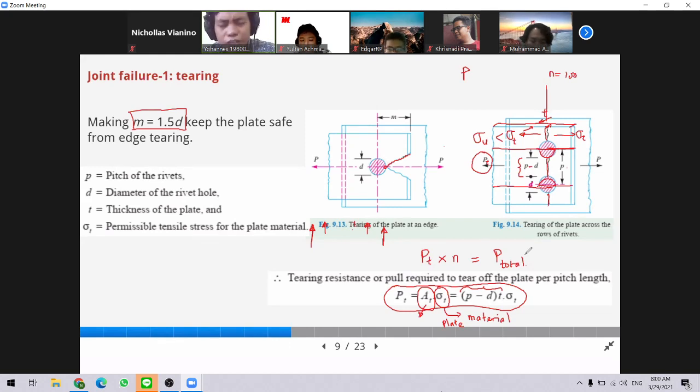Even if we use very thin plate, it still has a bending moment working there, even if it is small. And even if it's small, it can still bend the plate because the plate is very thin and becomes very elastic. So if we want to avoid the bending moment in the joint, we cannot use a single lap joint, we must use a butt joint. Okay, so that's about the bending.